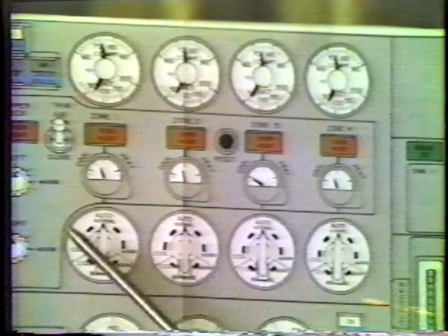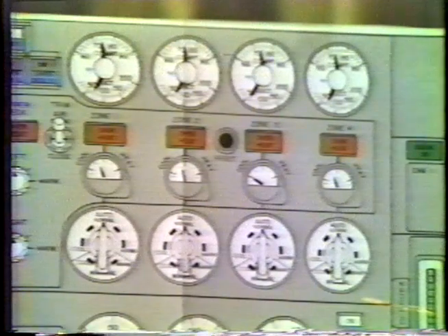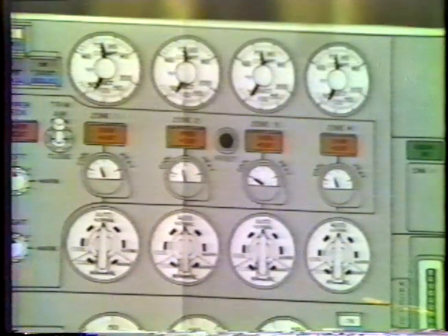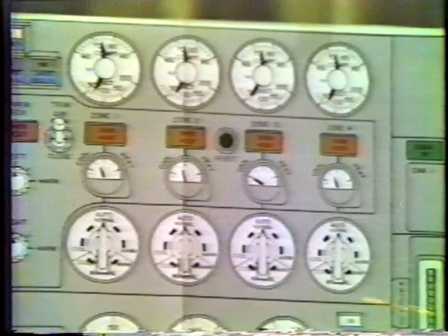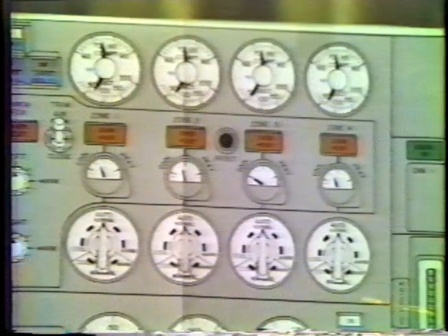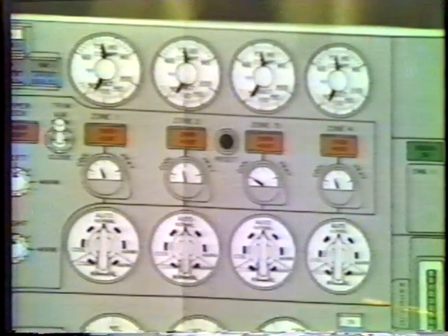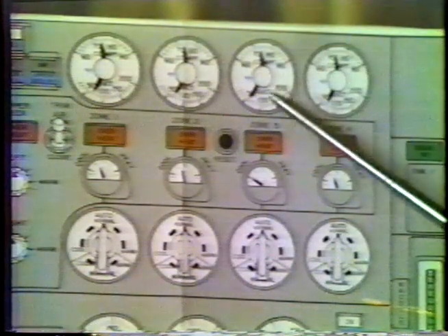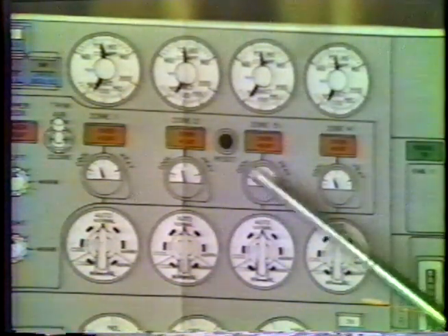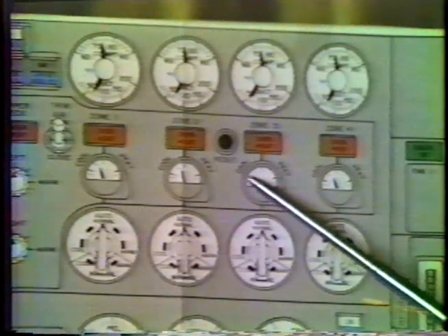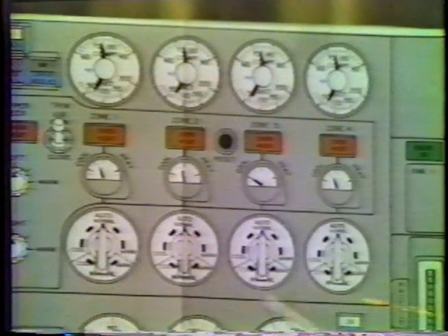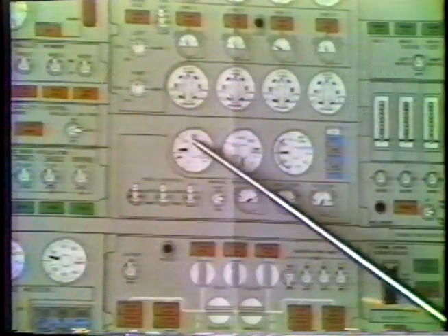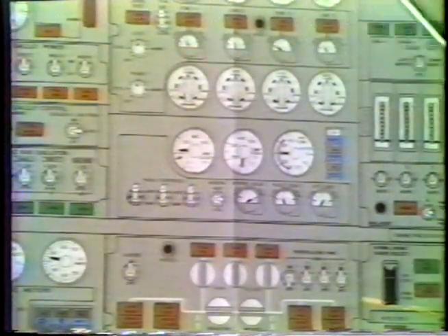When selecting the temperatures here, the area that requires the coldest air to condition that area will be the controller that is controlling the 3 packs. For example, let's say we had 200 people in the center section of the airplane, and that would be zone 3, which would require the coolest air. The trim air valve for that area would be full cold. That in turn would tell the packs the temperature of the air out of the air conditioning units necessary to control that zone.